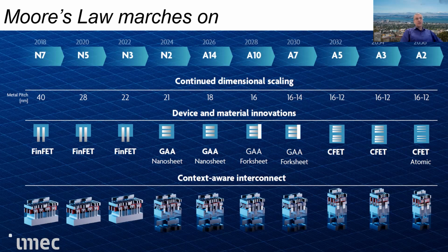Even though it's called the 3 nanometer node, in fact, the structures we make on the computer chips, that you're going to see in exquisite detail in the final talk today, are only 22 nanometer lines that are separated by 22 nanometers. So the naming convention is a little funny in terms of what we call 3 nanometer node, but that means that we still have a lot of room to push things further.